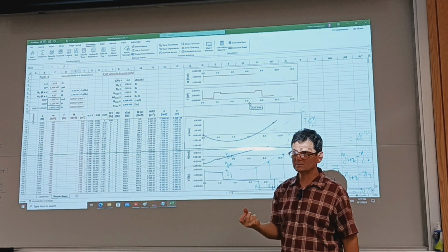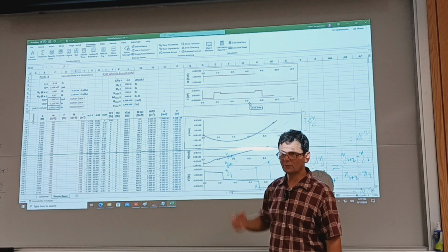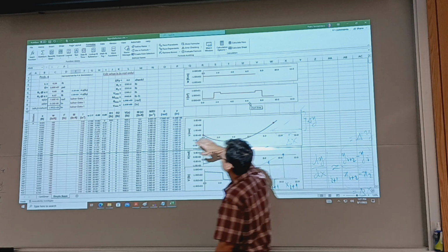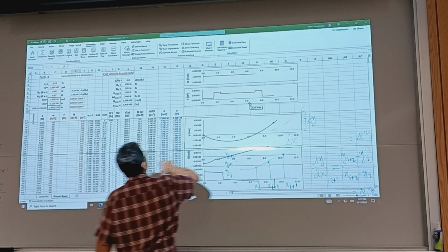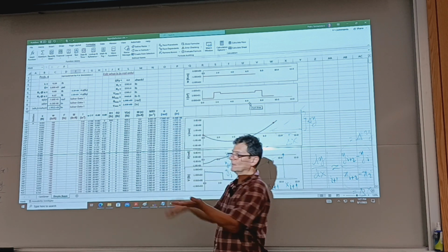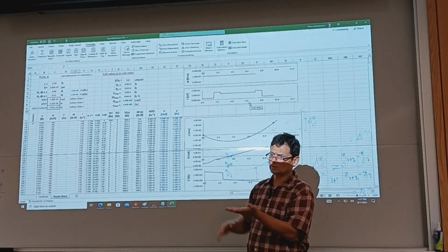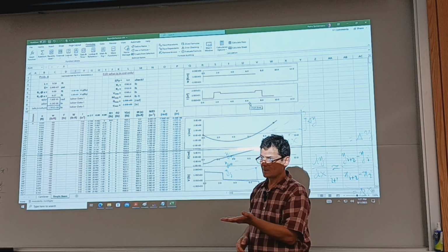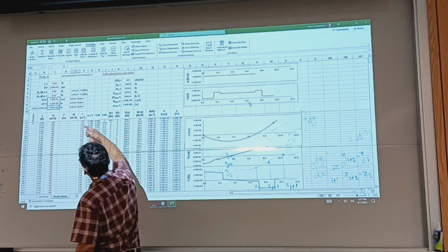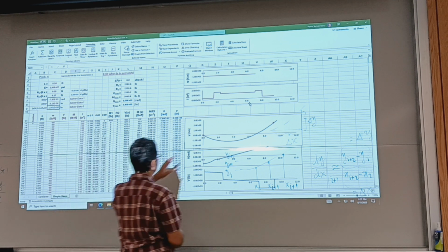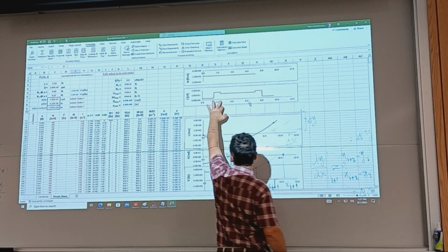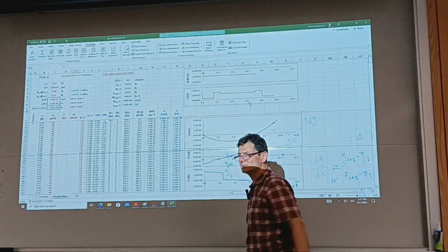So in case of a stepped shaft, do you follow? I'm wondering what you're doing. You're watching me on YouTube, or so the last column here is where you place the moment of inertia. And the graph shows you just the top half of a longitudinal section. Does it make sense? If I is the same throughout, no big deal. But if you have sections of different area moment of inertia, you verify against this graph and say, yeah, I have it, it's where the bearings go. This is a shoulder. There's a portion in between. Does it make sense? Okay.